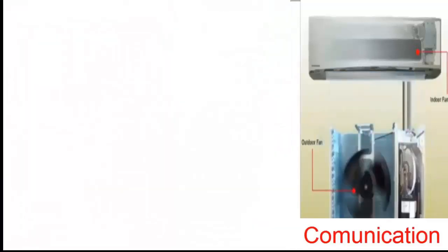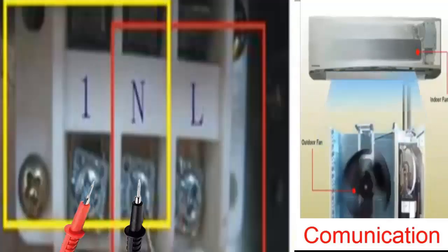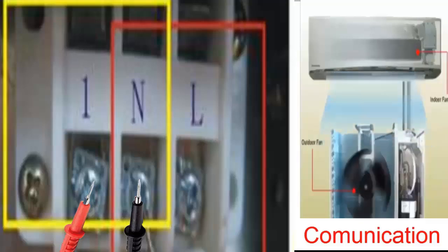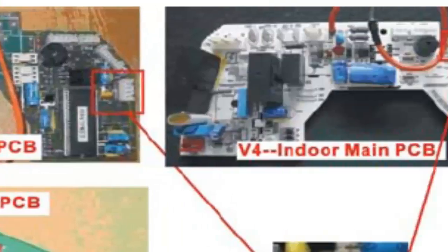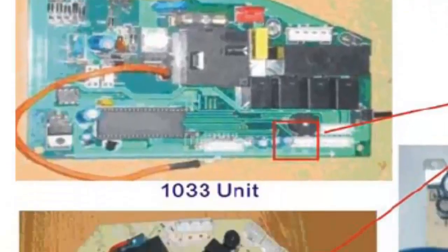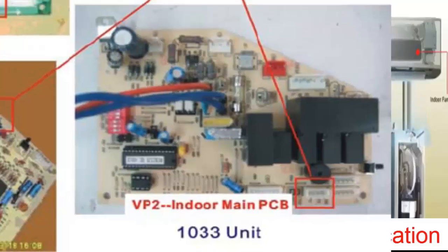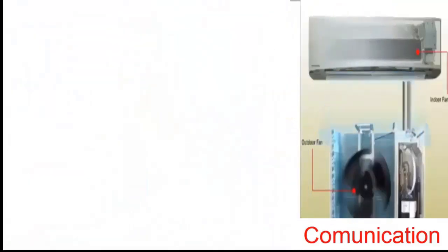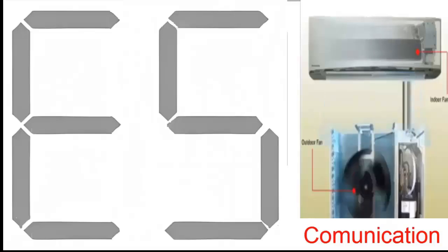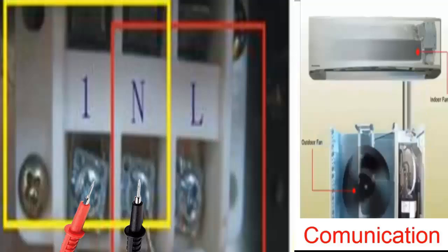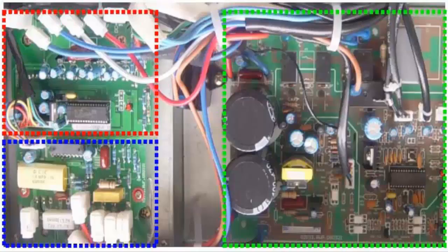6. If the voltage between L and N is normal in the previous step, measure the voltage between the N terminal and terminal 1 on the outdoor unit. If there is a voltage change between 0 and 24 volts, pulse voltage, the problem is likely in the main indoor PCB. 7. If there is a voltage change between 0 and 12 volts between pins N and 1, pulse voltage, but no 24V, the problem is likely in the outdoor power supply.